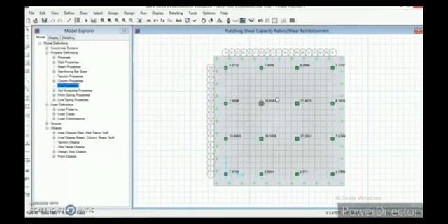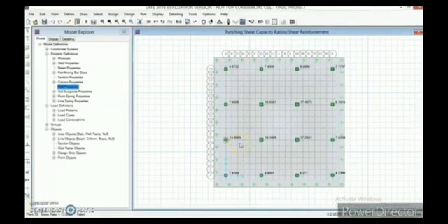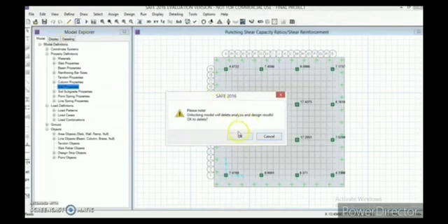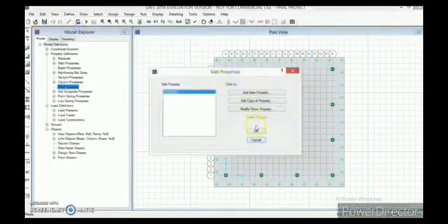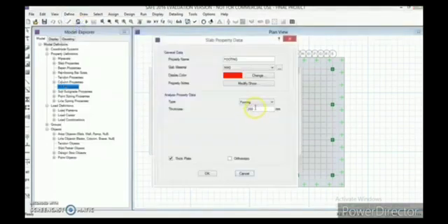So we need to change the thickness value. So now let us modify this, because as the punching values are greater than 1, it is a failure. So in order to make it a success, unlock it, and unlocking the model will delete the analysis, click on OK, and after that go to define slab properties, modify or show properties, and thickness here is 200 mm, and let us change the thickness to 900 and click on OK.